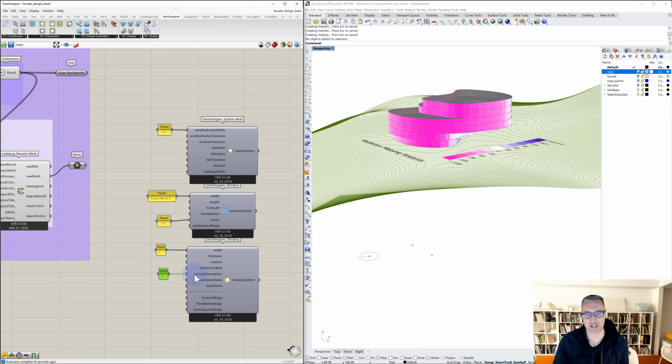Setting it to 1 will make it vertical. And let's add another 0 or 1 to window shade. Setting it to 0 is false, so that our shading element will be the entire width of the panel. As we change this to 1 to be true, the shading device will only be over the glazing. Just trust me, we'll see how these work, and we'll come back in a second.